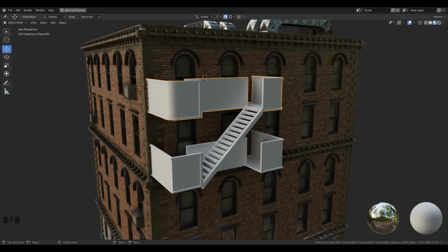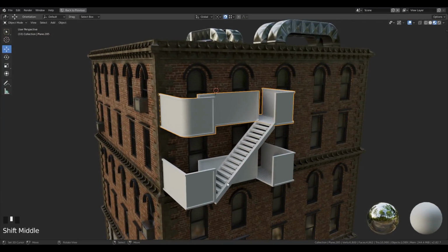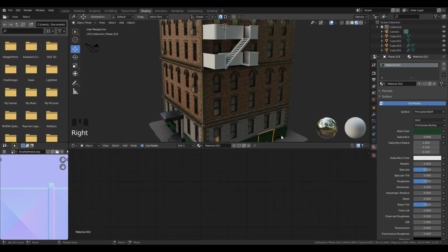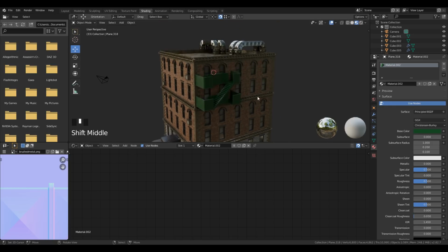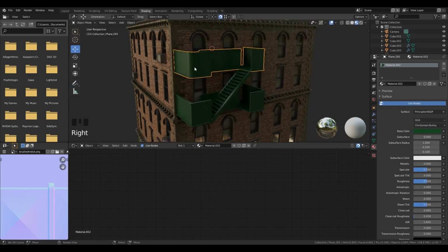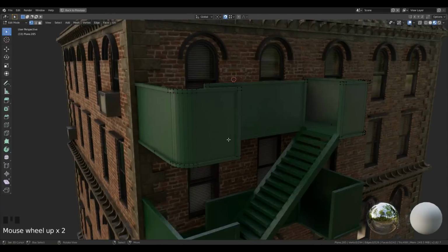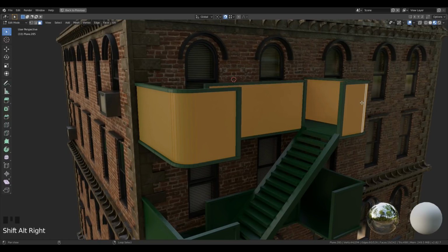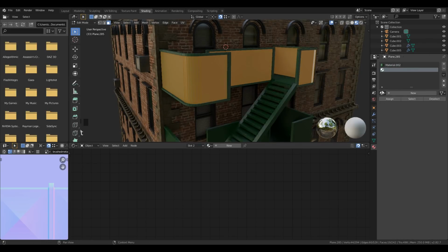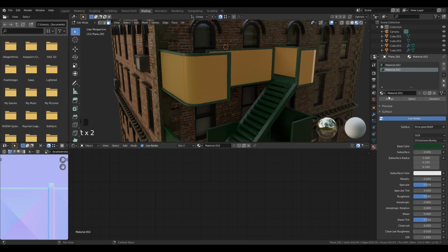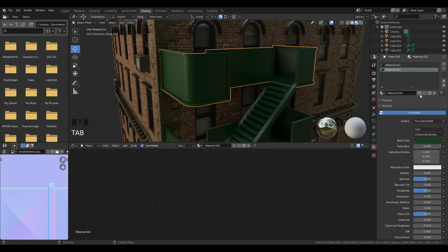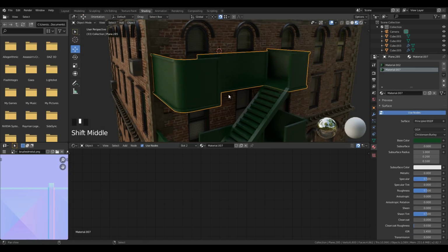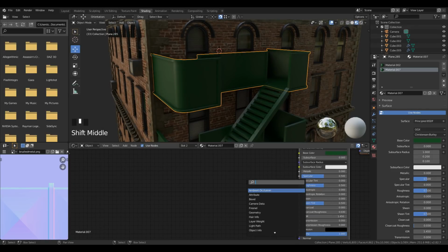After that, switch back to scene 1 and apply the same green material which we have used for the bottom of the building. Select the mesh and drag and drop the material on the stairway meshes. Then select the top mesh and in edit mode select the middle faces of the mesh and add a new material slot by clicking on the plus sign. Now add the same green material, then make it a single user copy and assign it to the faces.